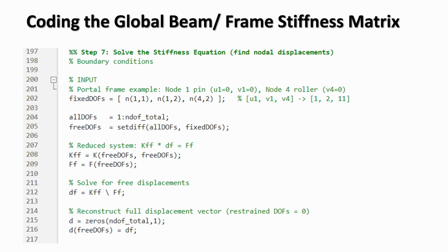As we know, each support limits certain movements, so a fixed support would prevent all the translation and rotation at that node. A pin support would prevent all horizontal and vertical movement, but would allow rotation at the node, and a roller support restrains movement in one direction only, while permitting movement in the perpendicular direction and rotation at the node.